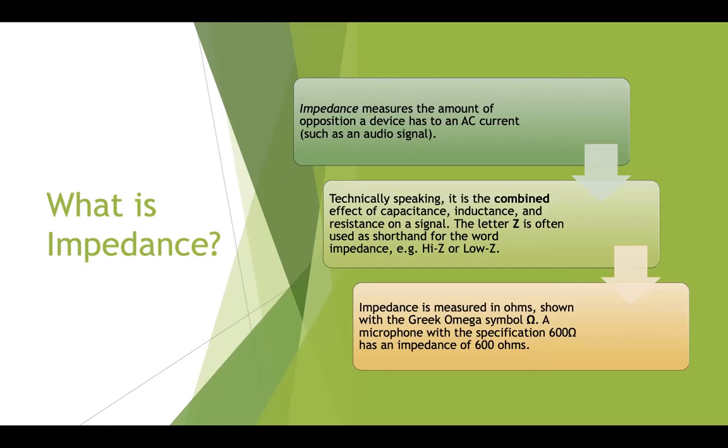Resistance is the quality of a single device, such as a wire, a light bulb, a speaker. A single thing has resistance. The combined effect of the resistance, capacitance, and all the other forces that slow down electron travel through a device is called the impedance, okay? So to use an example, home theater speakers would have 8 ohms of resistance because the speaker is a single device. The impedance of the amplifier driving those speakers would be another number altogether, right?